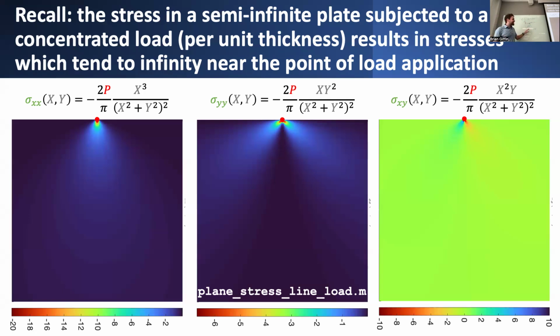But in point of fact, that's only applicable up to the limit at which the material can maintain this linear relationship between stress and strain. If you exceed some critical value of stress, then you really can't believe anything that's happening in that region. So anywhere in this domain where the stresses would exceed some critical failure stress, we can safely say that that's just not physical.